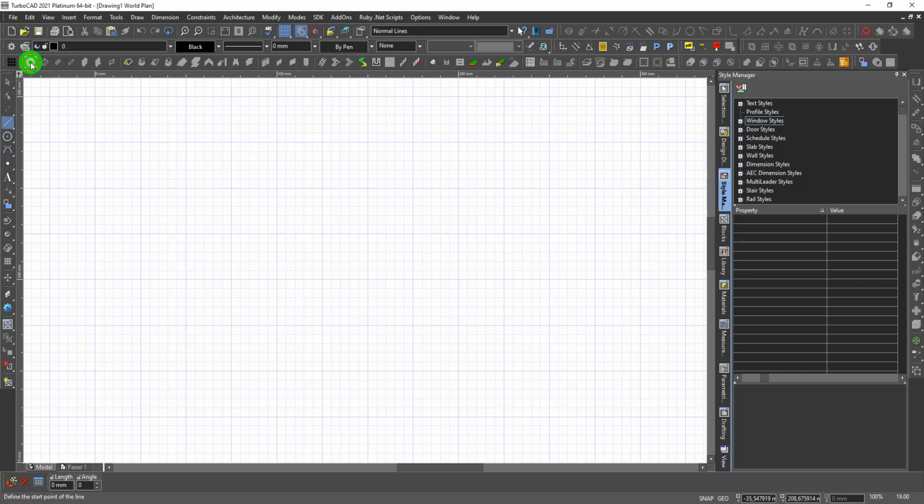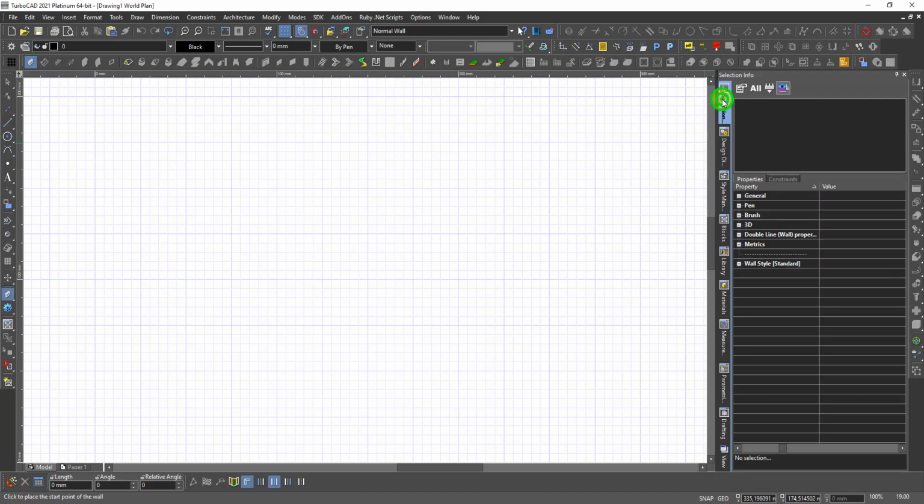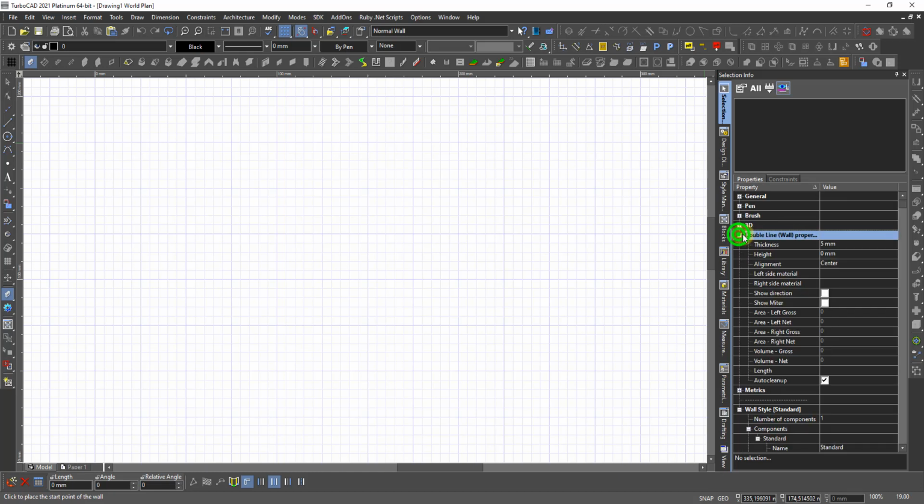I just make a simple wall, and then I change the standard wall. There's nothing to it, I should only go here, and I want 215 as the thickness. The height should be 2663, and I use baseline.